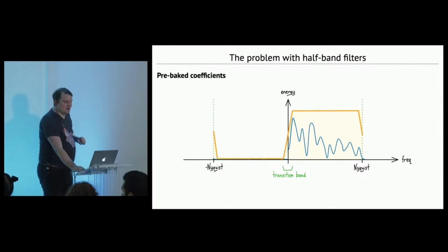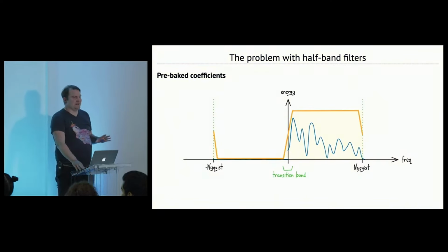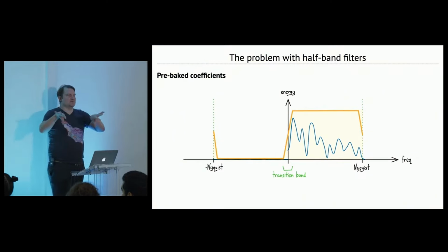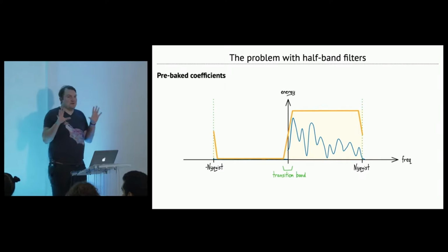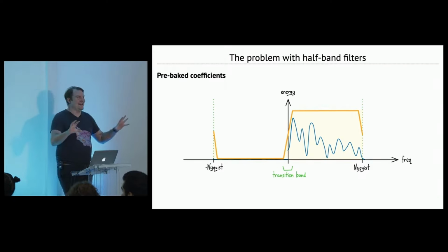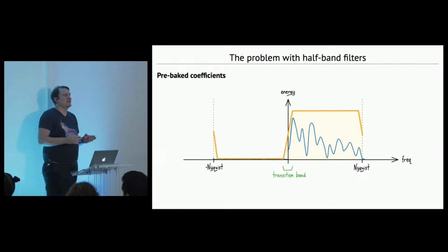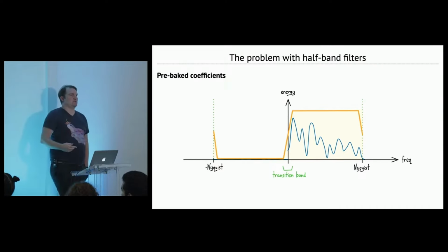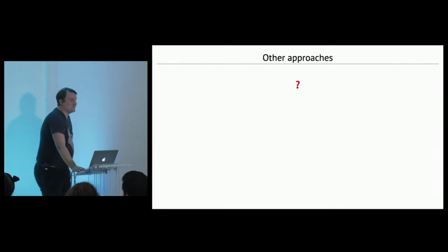So when you've got this kind of all-pass setup, what it's almost certainly really doing is an elliptic filter, which have a very nice property that, under certain circumstances, you can separate them into two parallel all-passes. I'm mostly saying this to try and inoculate you against it, because if you see this kind of dual all-pass setup, no, it's doing a half-band filter, and it's subject to this problem where it gets worse at higher sample rates. So, what can we do?